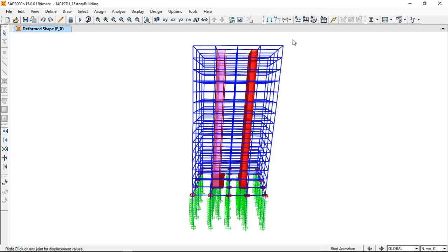If you take a particular floor, the displacement in the x direction, u1, should be the same value at each node. So if you consider this floor, the displacement in the one direction should be the same, because you want to act the floor slabs as rigid diaphragms.